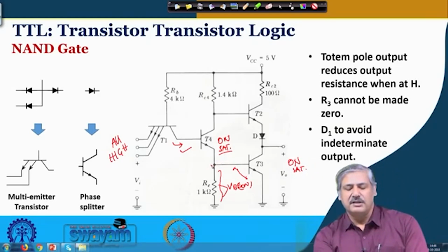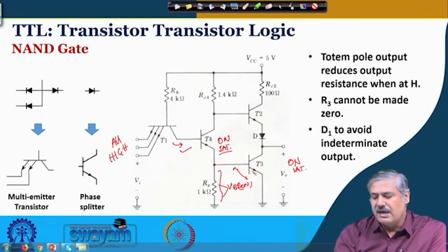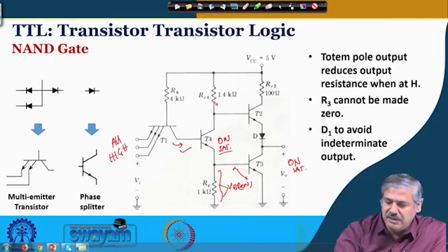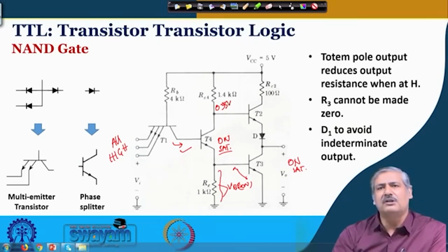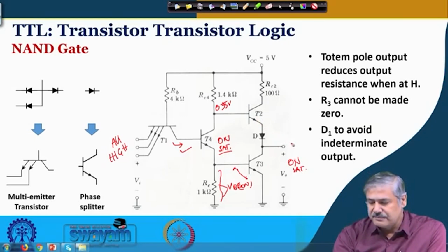So, what is the voltage then available over here? This is saturation 0.2 volt and this is saturation 0.2 volt, 0.1 volt and of that range, and this is 0.7, 0.75 volt. So, about 0.95 volt is available over here. Let us consider say 0.95 volt on the higher side. Now, with this particular voltage, here it is 0.2 volt, because this is in saturation.